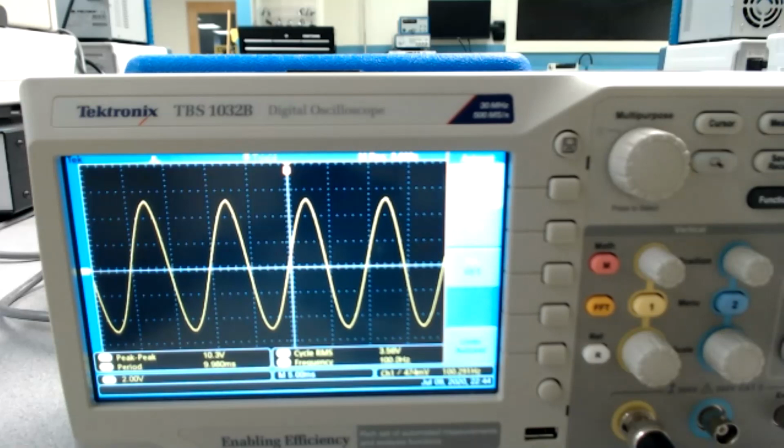If you would like to continue, Paul, please. Vary the output frequency from 100 hertz to approximately 1 megahertz in 10 to 15 steps. At each frequency setting, record the voltage on the oscilloscope and on the digital multimeter. Great. So right now, I'm going to open up a spreadsheet, and I'm going to share it.